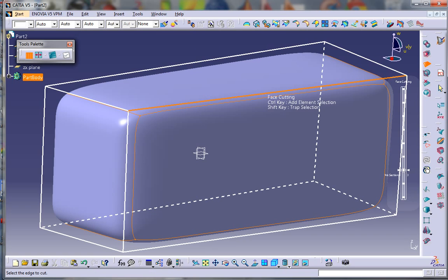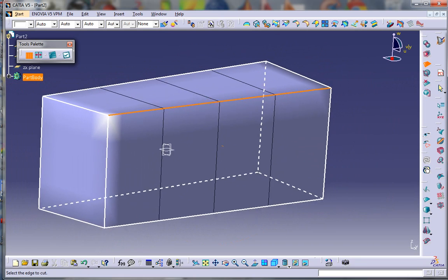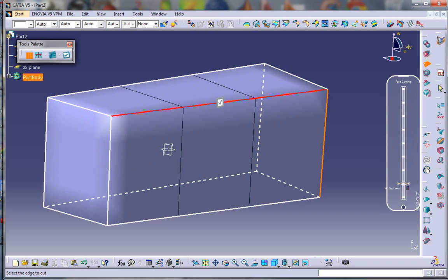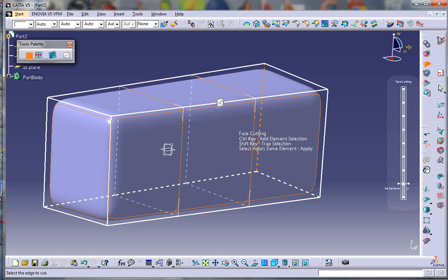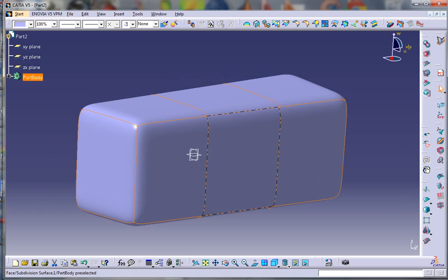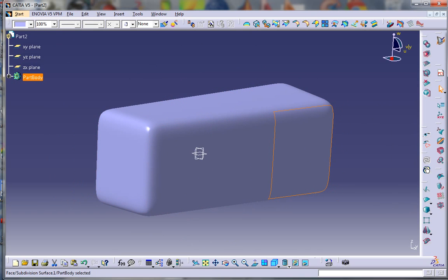And that tool is the face cutting tool. The face cutting tool is very important, as if you click a line anywhere on the body, it subdivides the entire body into different subsections, and you can choose how many subsections you want by the scale. The more subsections you have, the better, as you can manipulate the body even more. But for now, we're just going to do 2 or 3, and after you select, you have to click the enter button. If you click 2, it creates 3 subsections. You can even do more for different parts of the body.